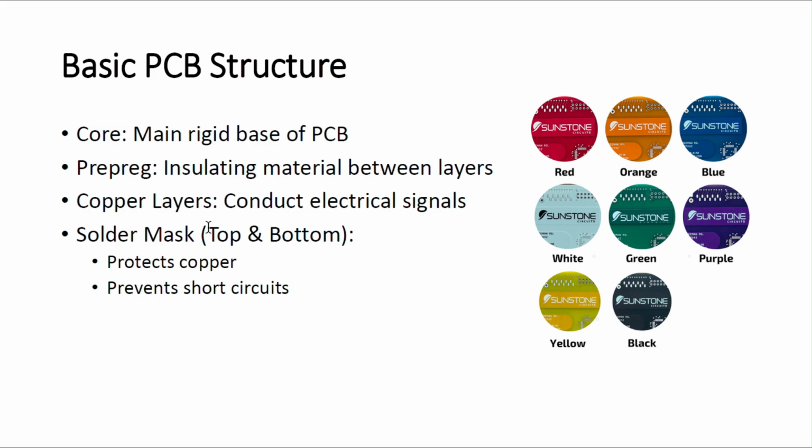So we use the copper layer, and the copper layer will undergo oxidation problems. These can be avoided by including the solder mask. So generally everybody uses solder mask material. In older technology, people used to not include the solder mask.